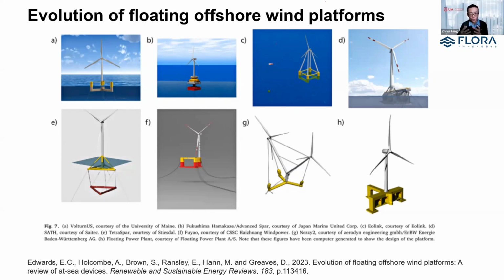The idea is that we can use conventional steel tubes as the basic Lego elements of the foundation, and we can do the mounting and the installation at the key site, so that everything can be done at a low cost. And because the steel tubes can be mass produced, the manufacturing cost is also relatively low.